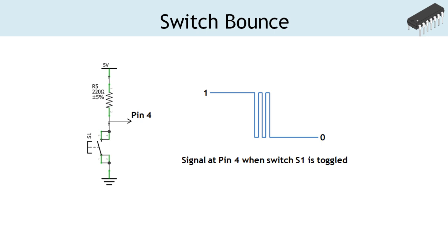It can be handled by using a switch debounce circuit, which is a highly reliable solution. It can also be handled by introducing a delay in software just to ignore the switch bouncing. But it is not the best solution. For me, it hasn't been a major issue, so I shall use the second option, which avoids increasing the complexity of development circuitry. I shall use a delay of 100 milliseconds in the ISR to ignore the switch bounce.